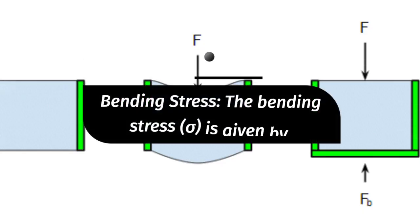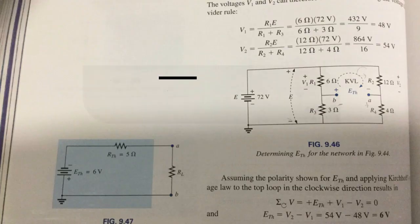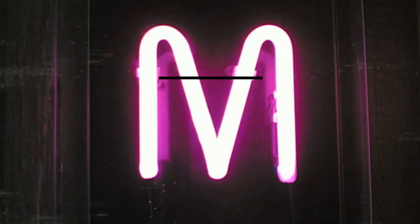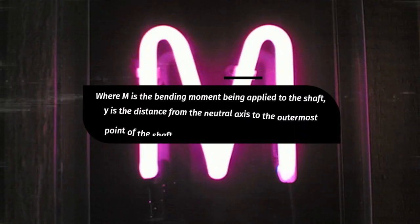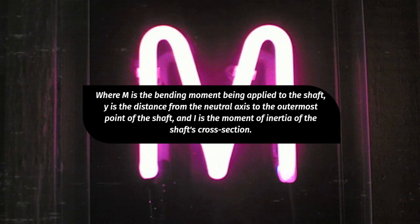Bending stress. The bending stress, sigma, is given by sigma equals My/I, where M is the bending moment being applied to the shaft, y is the distance from the neutral axis to the outermost point of the shaft, and I is the moment of inertia of the shaft's cross-section.